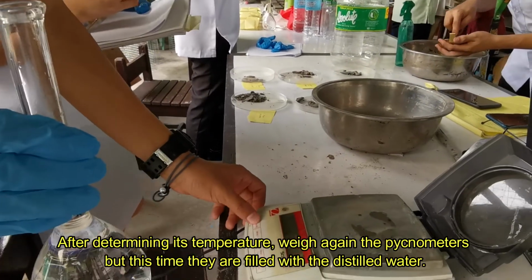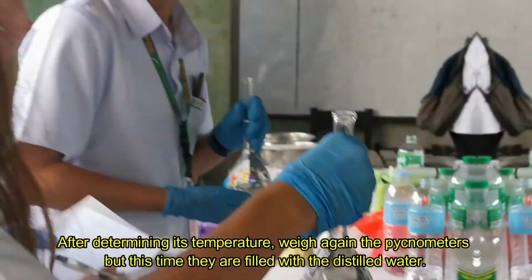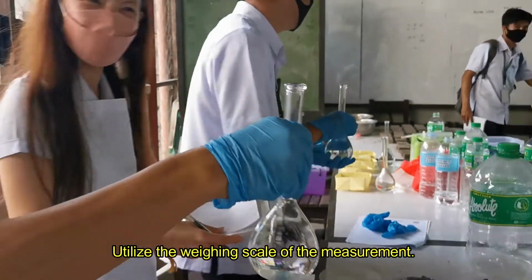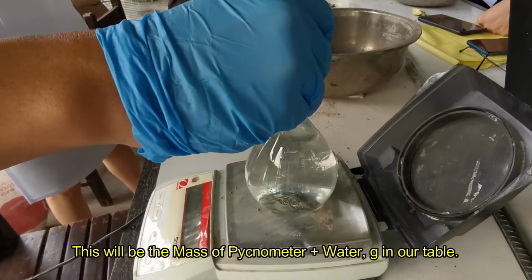After determining its temperature, weigh the pycnometer again, but this time filled with the distilled water. Utilize the weighing scale for the measurement. This will be the mass of pycnometer plus water, in grams, in our table.